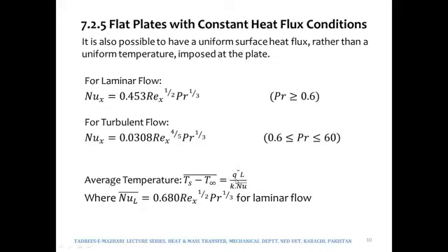And we would also have the Nusselt number in the denominator. So if we use the expression Nusselt number is equal to hL over k, using that expression we can then write h in terms of Nusselt number, k and L. So this is a very easy expression which you can write yourself using Q is equal to hA delta T, and then writing h in terms of Nusselt number, using the Nusselt number is equal to hL over k expression.